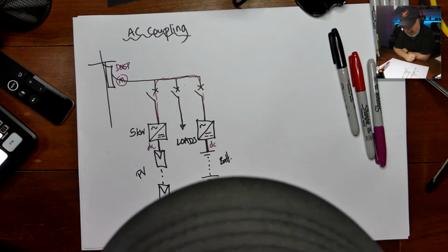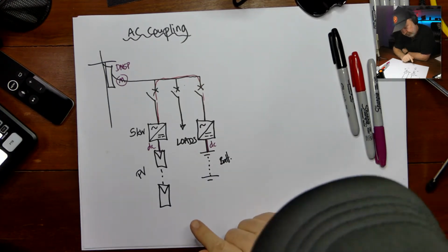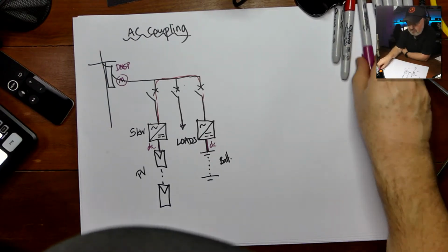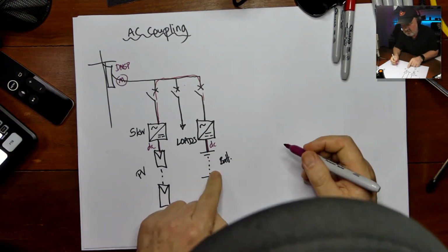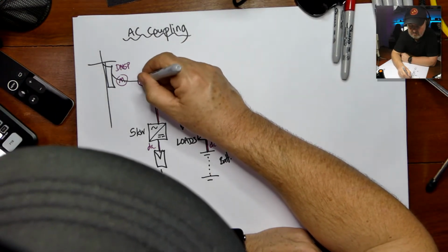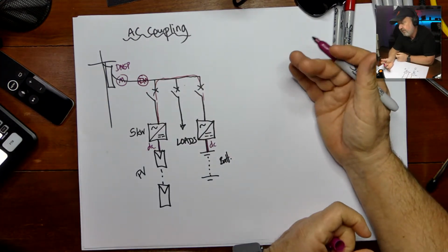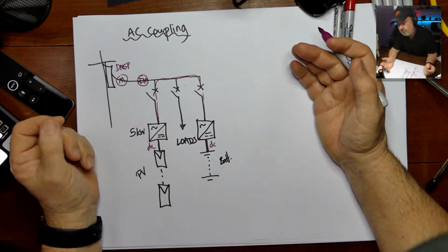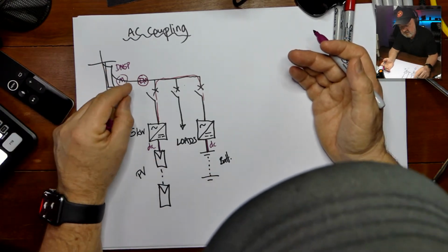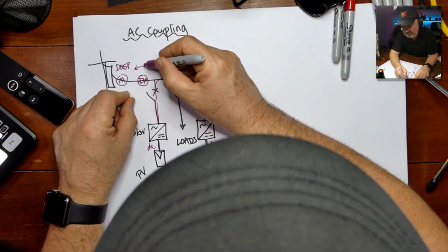And you might go, Glenn, hang on, why did you even bother drawing it? It won't work until we put in one other component, and that is the energy meter. Now, the energy meter is supplied with the storage inverter, so I'm going to put it here and call it EM, energy meter. And so it's an additional meter. It's not the DNSP's meter. It's not the one that you pay your power bills on. But this energy meter allows the installation to see which way the energy is flowing. Is it flowing out, or is it flowing in?